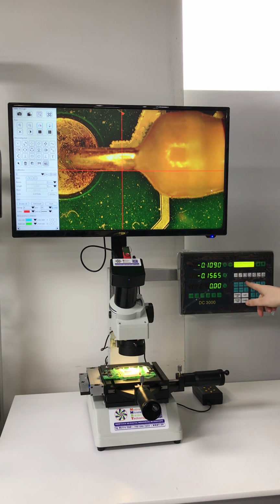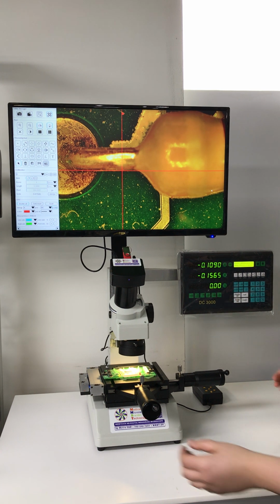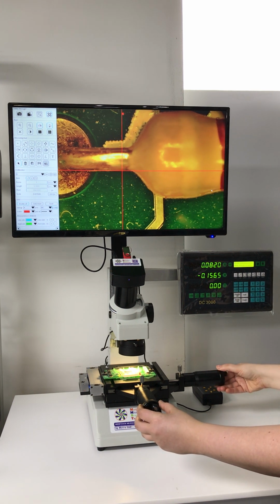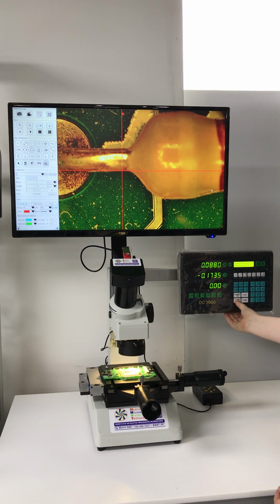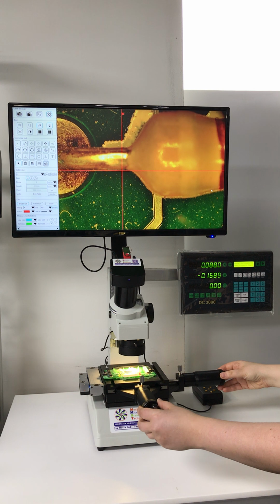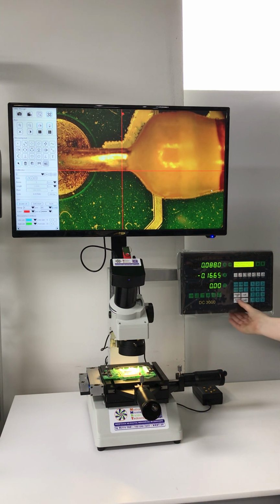And if at any point you want to do rectangle, we also can do more. Go to the setup, go down to special measure and press enter. Press down to do rectangle measurement. And for rectangles, we'll do 5 points. So again, focus on your part. And always, for the most accurate measurement, line up your part with the crosshairs.